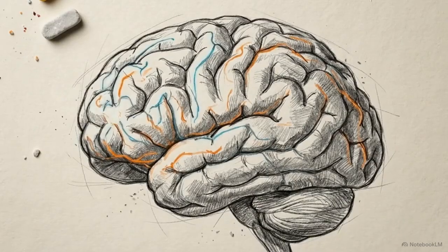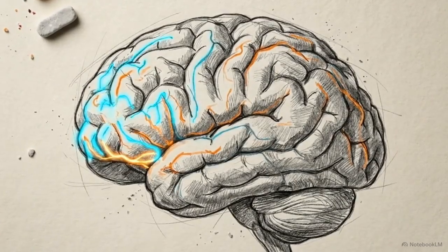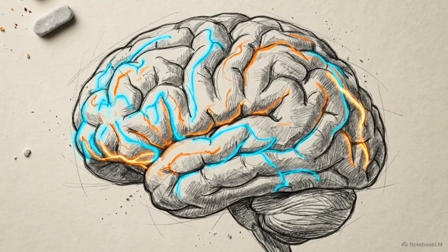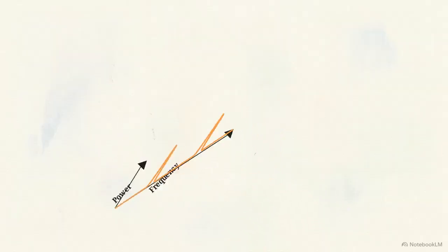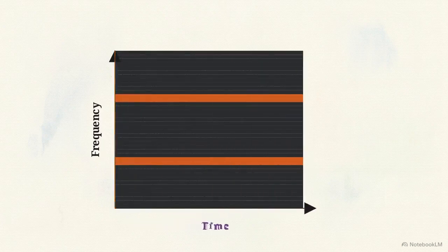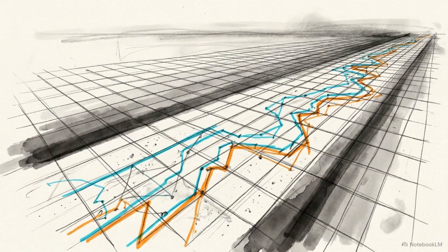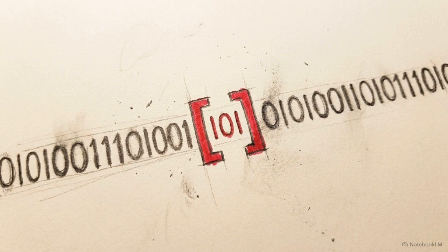This makes the FFT insufficient for audio or EEG data, where the sequence of frequencies is what actually carries the meaning. To fix this, we have to use a spectrogram, a compromise that trades some frequency precision to regain that lost temporal localization. Solving the when problem requires moving beyond the flat two-dimensional spectrum to track how frequencies evolve across the axis of time. The second blind spot appears when we are forced to work with extremely short data windows, sometimes as few as 64 samples.